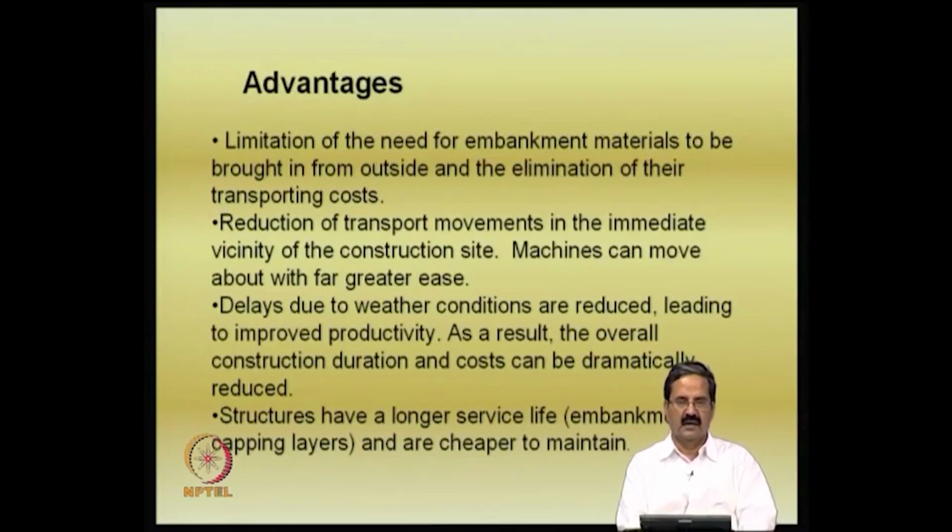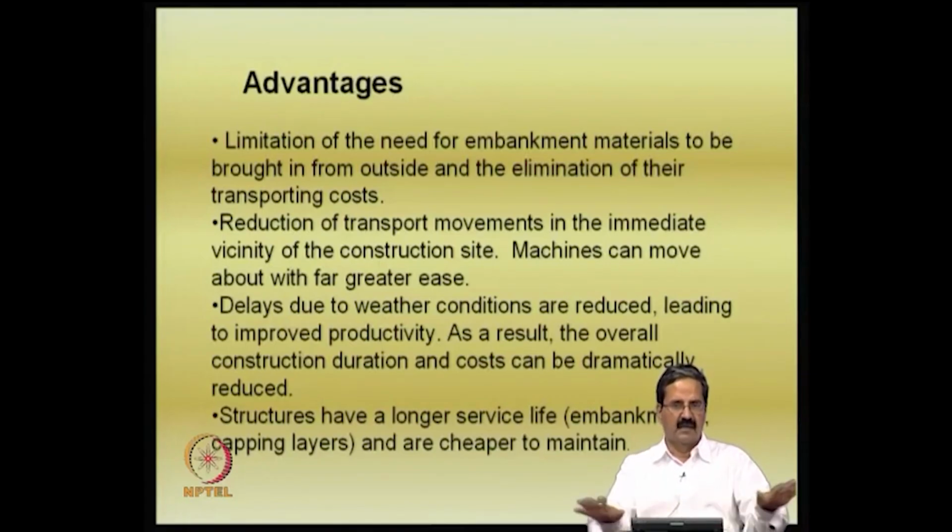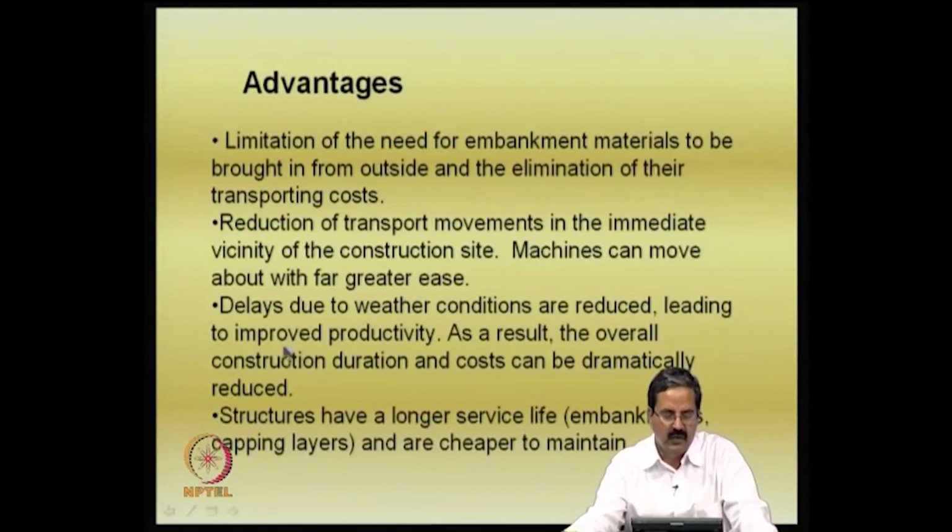In warm climates, how much time should you wait? Just 2 hours is sufficient. You sprinkle the lime on that material and mix it, and then that material becomes easy to handle; one can work with that. So, delays due to weather conditions can reduce, leading to improved productivity.